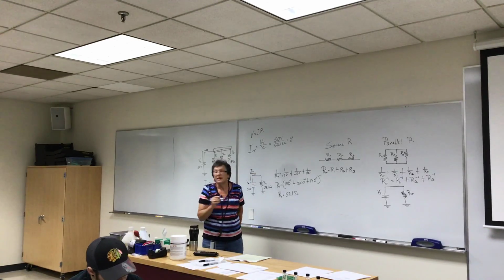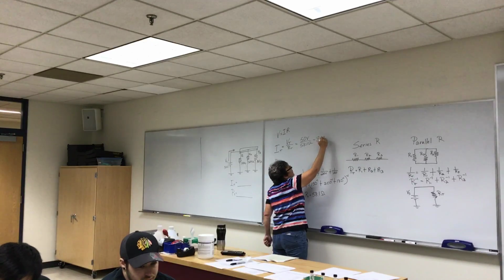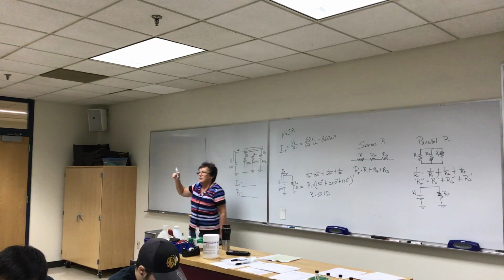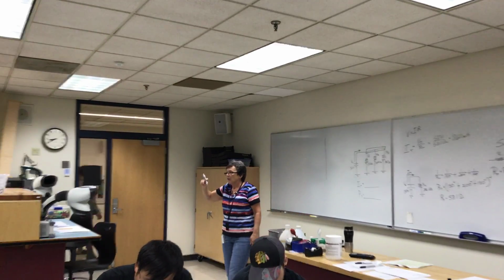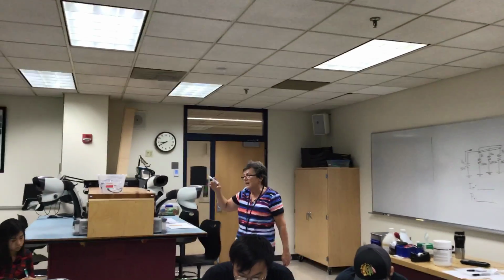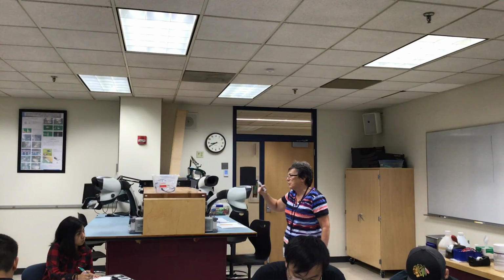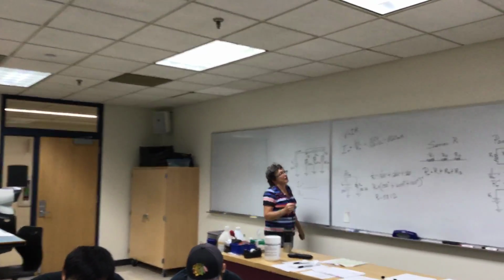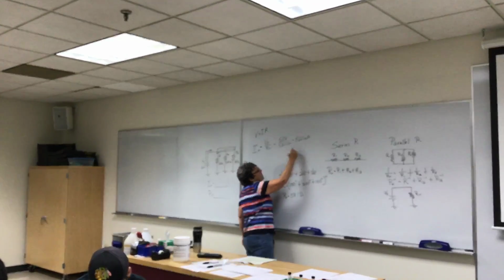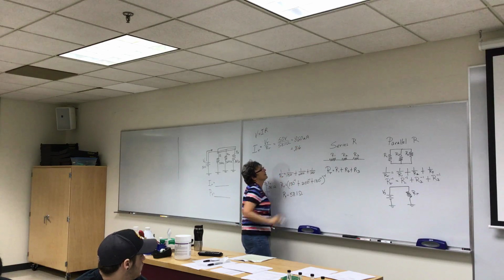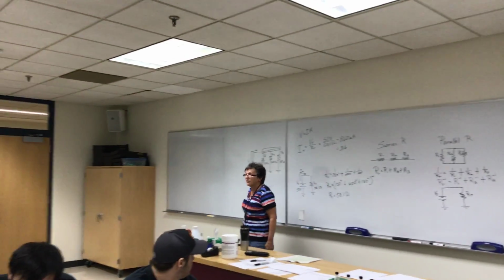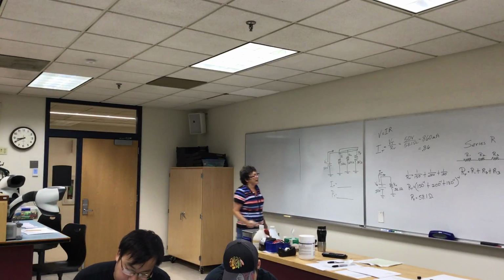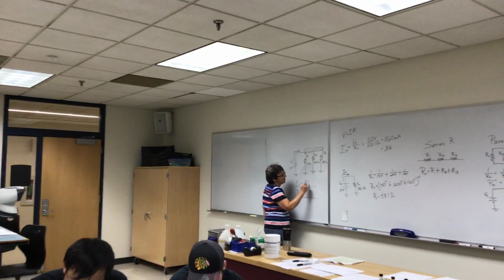860 milliamps. Do you have your calculator set on engineering notation? A lot of calculators you can set on engineering notation, but then you have to pay close attention. If you don't, your calculator is going to come up with 0.86. You have to know that, then be able to convert it to milliamps. 0.86 amps, so we got 860 milliamps.